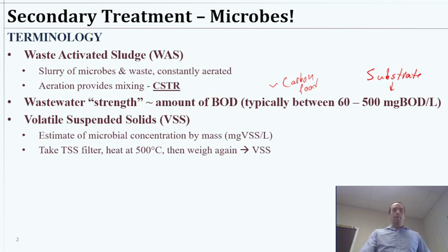So they should oxidize, they should be driven off as CO2, maybe nitrogen, other forms. You'll be left with a little bit of ash, perhaps if there were some minerals, but if we think about a bacterial cell, there's really not going to be a whole lot of mineral composition there. Most of it's just organic molecules. So essentially what we measure, when we take this volatile suspended solids measurement, is a crude estimate of the mass of bacteria.